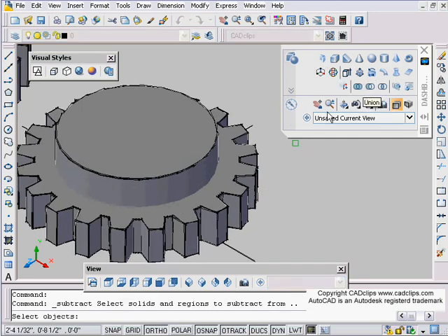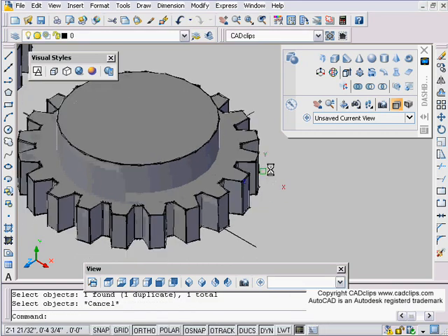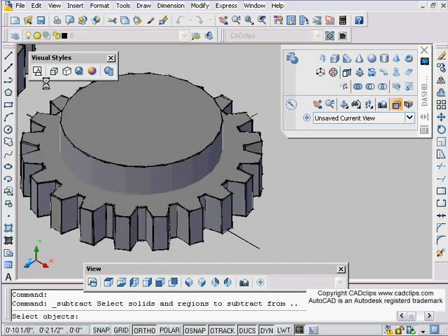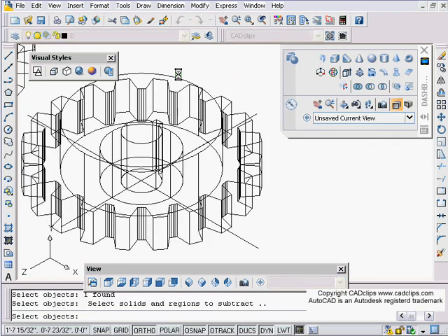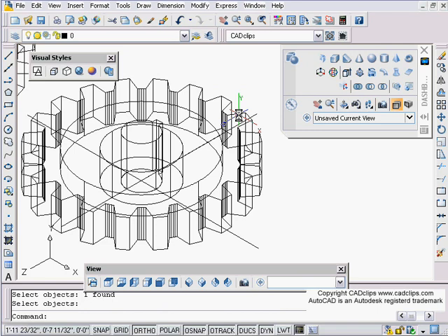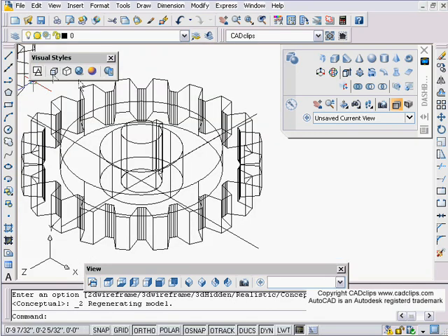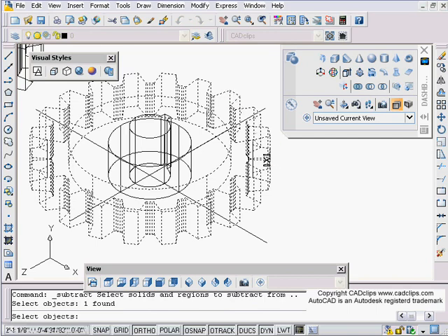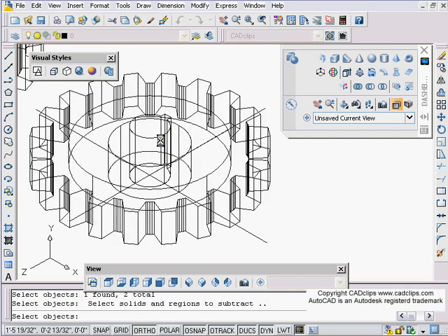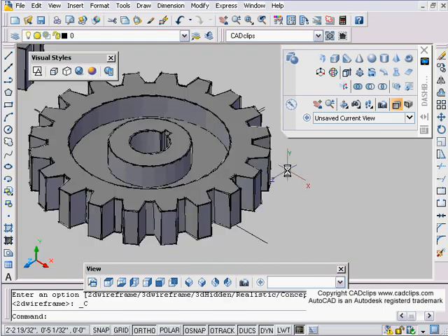So now what I'm going to do is use my subtract from here, enter, okay, I might have to use my object cycling here. Let's switch to wireframe and see. So let's go subtract from here, enter this, enter. Okay, so that removed that. Okay, now I'm going to go back to here. It seems to be easier to select. Now I'm going to say subtract from the big one and this one, enter this, enter. Okay, that's going to create the hole.